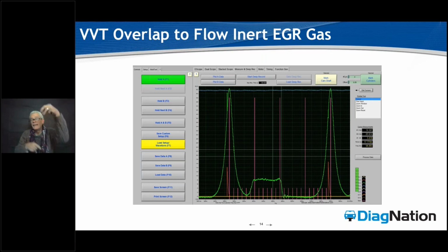Take that argument, intake, to the rings. Now the rings are sticking and diminishing in their efficiency to seal the compression. Now we're getting blow-by gases, rapid oxidation of the oil, transfer of fuel into the oil base, and we are breaking down the oil faster. What's the detriment there? Everybody out there is comfortable, including shops in a lot of these day and ages, with this 10,000 mile oil change interval, or waiting for the light to come on in the car.